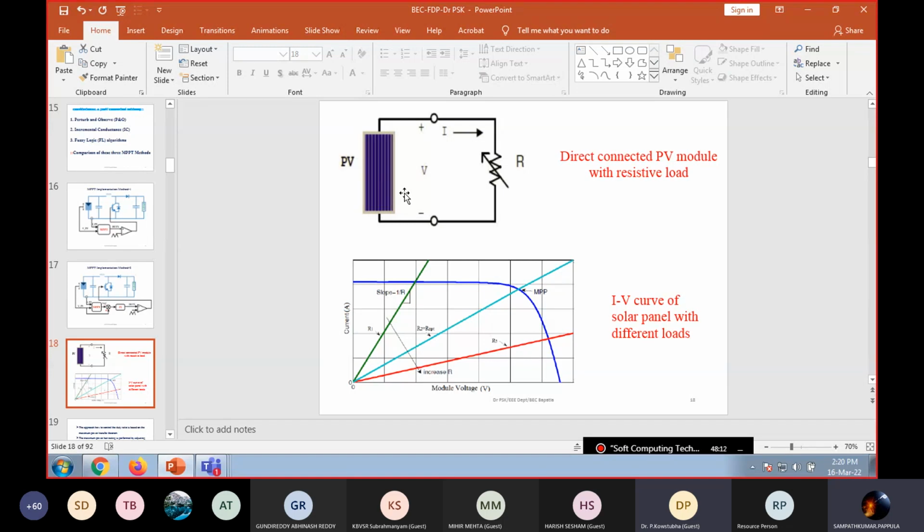To mitigate this problem and raise the efficiency of the solar system, an MPPT algorithm can be used to keep the solar panel's operating point at the MPP value, that is, the maximum power point value. The maximum power harvesting is performed by adjusting the duty cycle of the DC-DC converter. Duty cycle adjustment is performed with the MPPT algorithm.